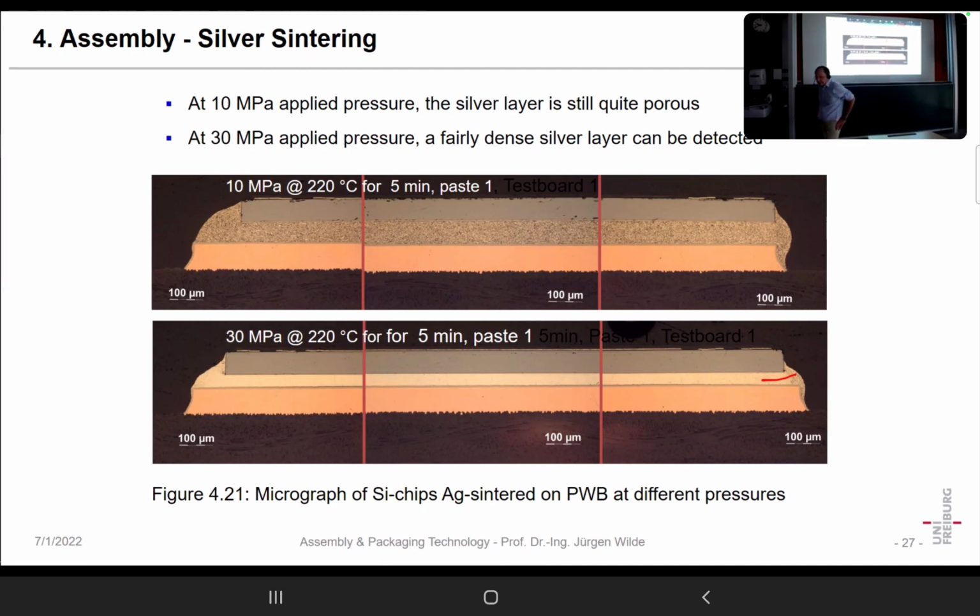One of the trends to lower thermal resistance in power electronics was making chips thinner. In the last 20 years or so, the thickness of such big chips was reduced from 0.5 millimeter, which was the standard chip thickness, to roughly 50 micrometers.